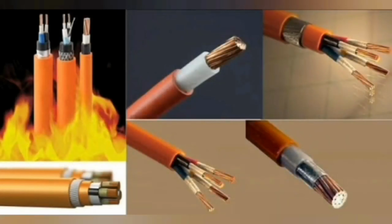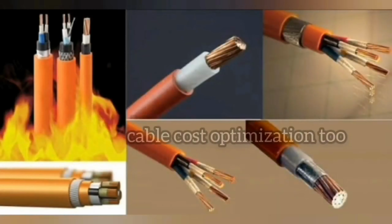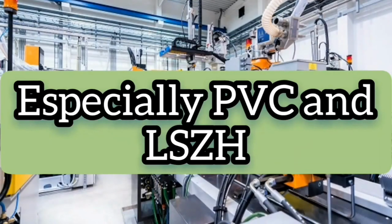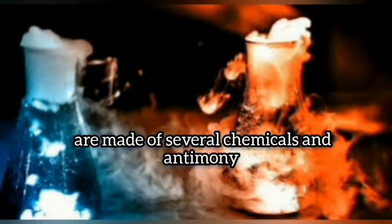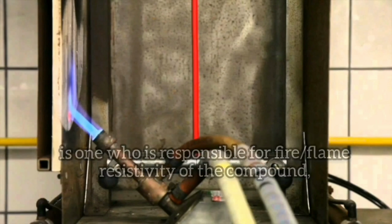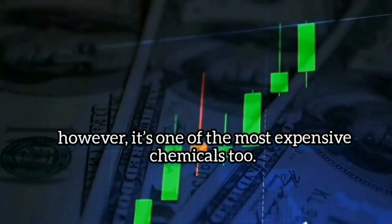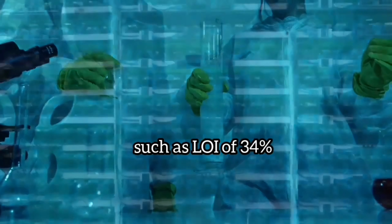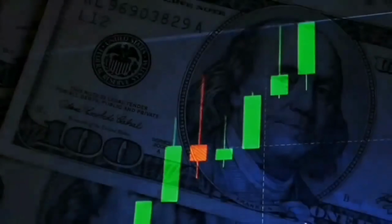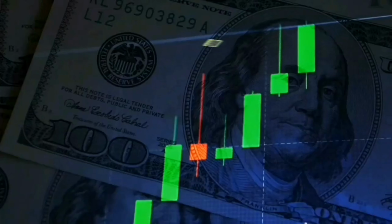This test also is very important, not only for flame resistivity of the finished cable but again for cable cost optimization too. Compounds, especially PVC and LSZH, are made of several chemicals, and antimony is the one responsible for flame resistivity of the compound. However, it is one of the most expensive chemicals too. So in case you do not require a very high flame resistance such as LOI 34% or likewise, you can always ask your supplier to optimize the level of LOI as well as cost per kg for the compound.